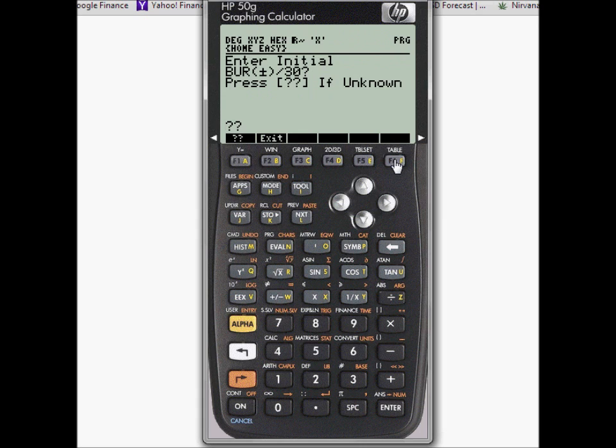So we know that the plan calls for a build-up rate of 4.5, and we know that we're 1.3 degrees behind in angle. So if we build at the proposed rate, we will be getting closer and closer to the plan line and at some point we might touch it, and then we will have to use a higher dog leg to actually hit the target. So I will first make an attempt to calculate this with a 4.5 initial build-up rate,